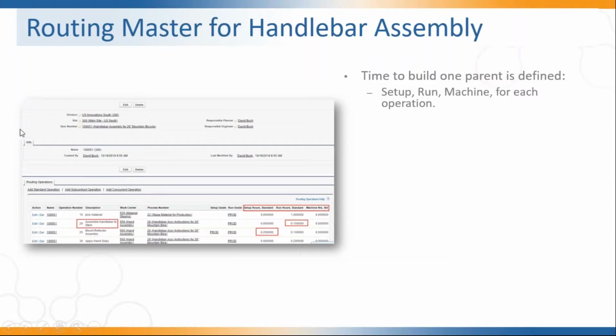So if you look down here at operation number 20, operation number 20 is to assemble the handlebar to the stem. And sliding across, we can see that setup time is 0. What that tells me is that there is no time required to set up or prepare this work center in order to begin work. If I was working on a drill press or a milling machine or some other machine like that, there probably would be setup time, as you see in the operation immediately below this one,